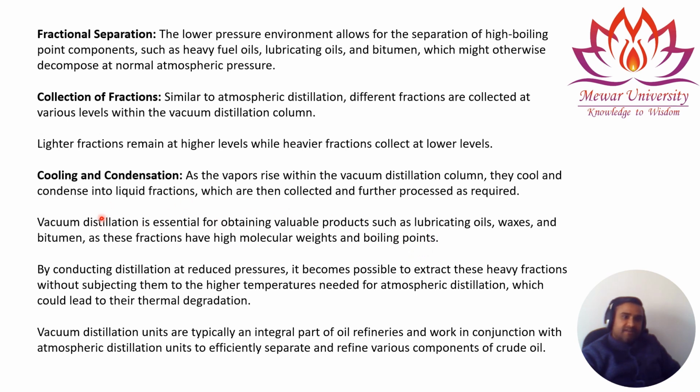By conducting distillation at reduced pressure, it becomes possible to extract these heavy fractions without heating them to the higher temperature that is needed for atmospheric distillation, which can lead to their thermal degradation, because with the application of higher heat they may be cracked or decomposed.